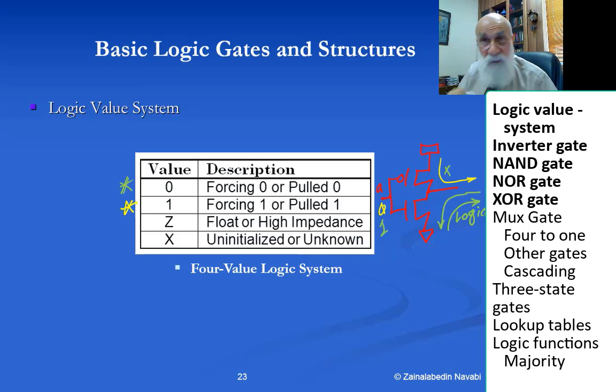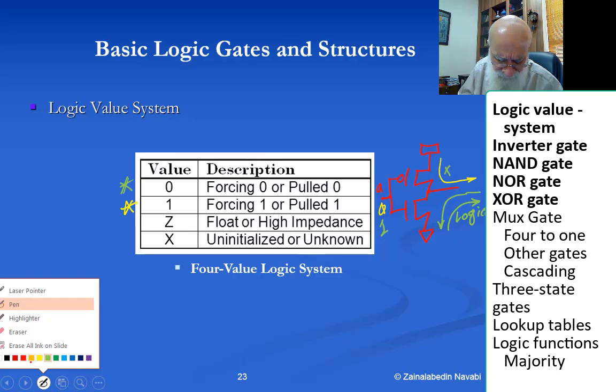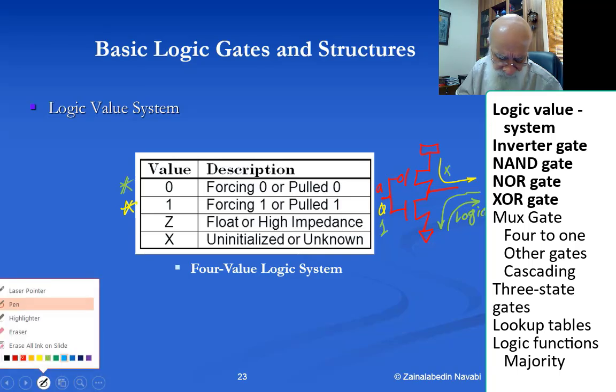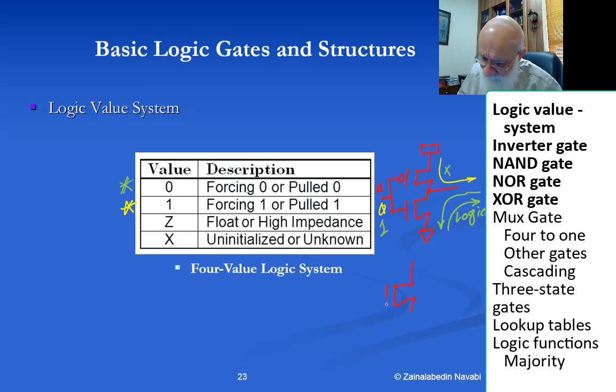All right, the two transistors have different delays. For example, when the input changes from 0 to 1, the upper transistor reacts slower than the NMOS transistor, which is the lower transistor. So there will be times that either none of the two transistors will be conducting. If none of the two transistors are conducting, let's, for example, look at this scenario. Let's try another inverter.